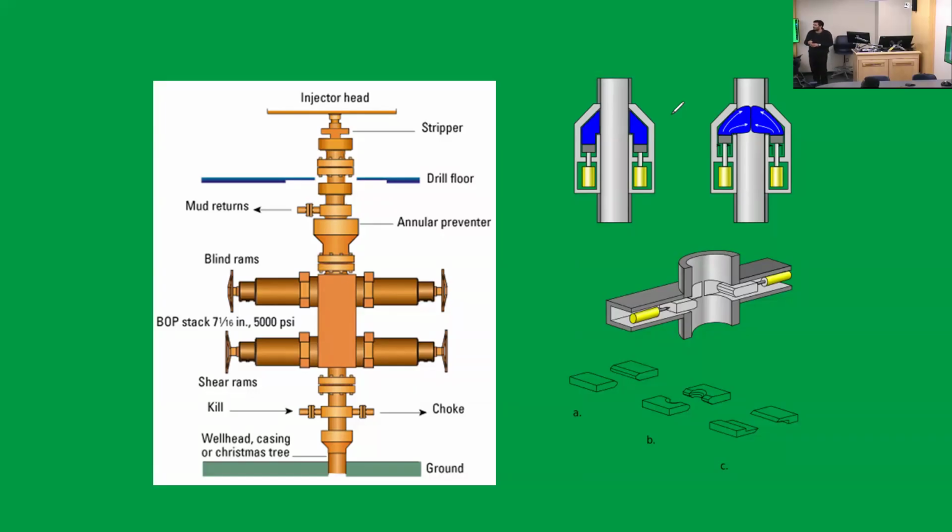But the closing, will it just grip the side of the pipe? For those, no, that would be the pipe ram. It just grabs the outside of the pipe, the annulus. That means a blowout can't happen through the pipe. It can only be through the drill string, so you need to basically cut the drill string and then shut it. Or in modern day, you have both together, it's going to cut and shut at the same time.